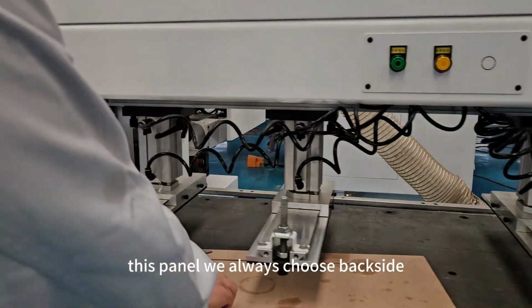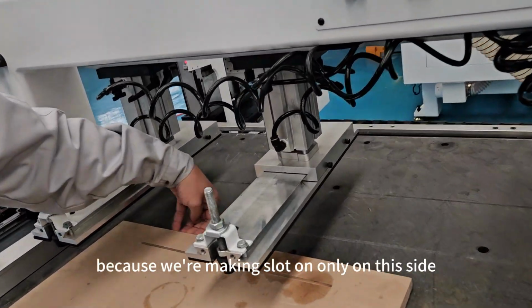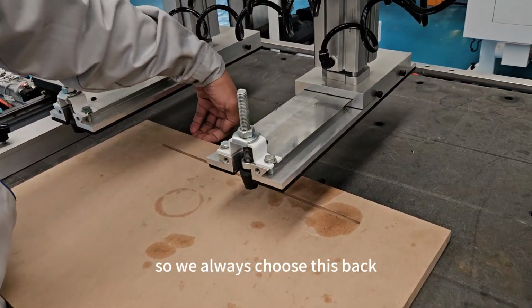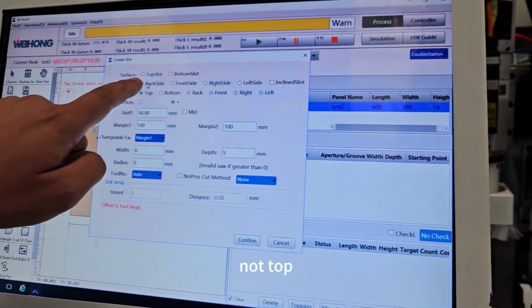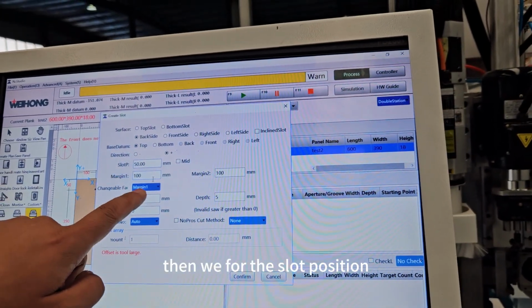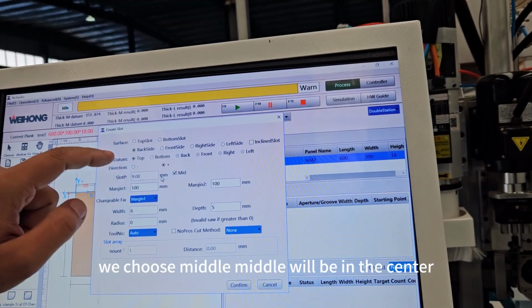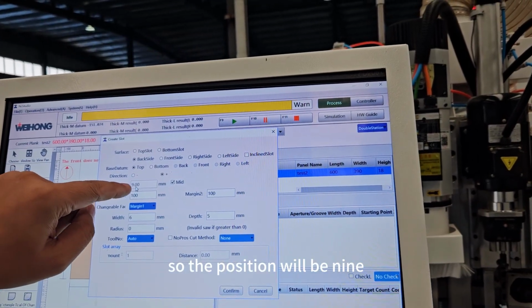For example, this panel, we always choose backside because we're making slot only on this side. This is forward. This is backside. So we always choose this backside. Not top, not bottom, backside. Then for the slot position, we choose middle. Middle will be in the center because the thickness is 18, so the position will be 9.